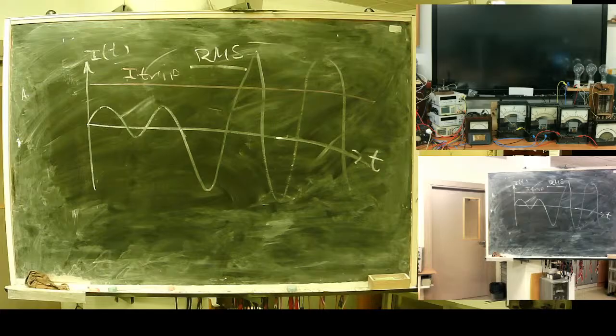What's inside simple circuit breaker? Thermal element, yeah? Thermal element reacts to effective value. It is resistor heated by current. For thermal element, it's not important what kind of current flows through it. Important is amount of heat producing, yeah? So it reacts to effective value. You can have rectangular current. Anyway, this is a miniature circuit breaker. For miniature circuit breaker, important is only amount of heat in its sensor.